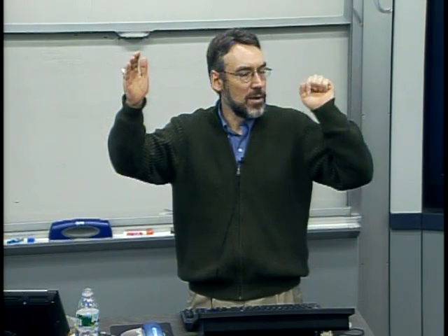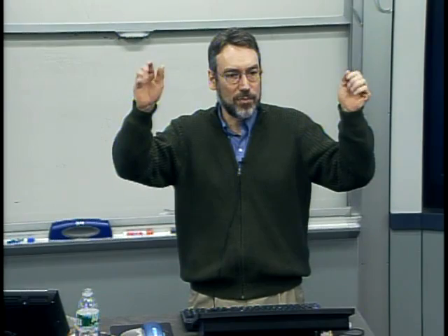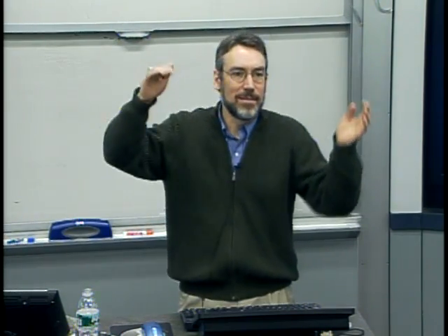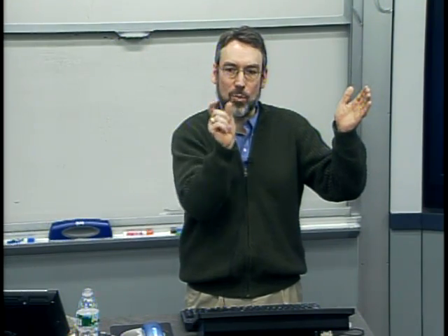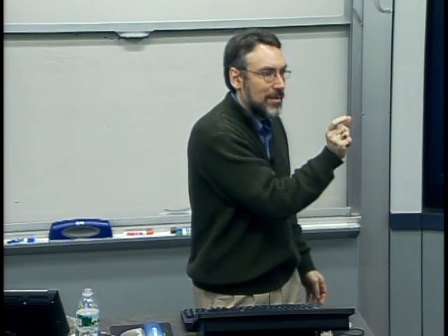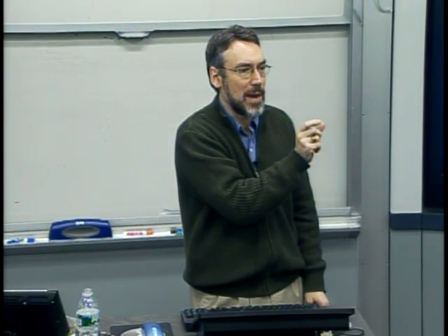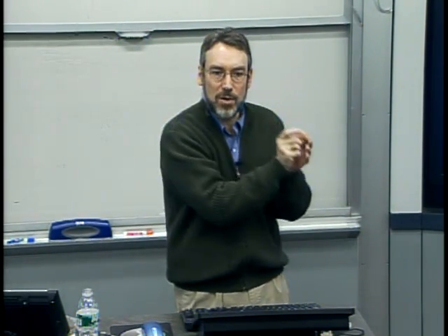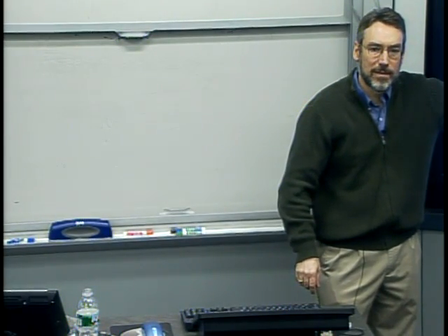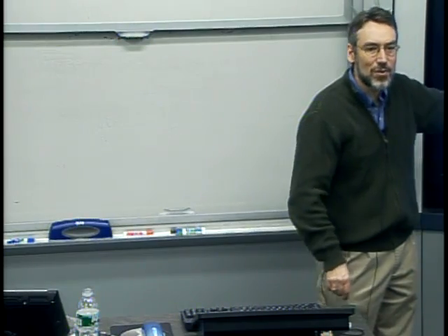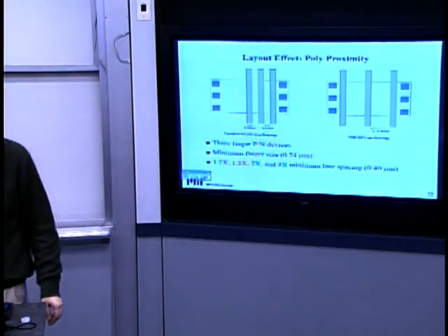If I were to say from center to edge, or from one edge of the wafer to the other, I have a systematic trend of about 10%, and I map that down to 1/10, because I've got 10 chips, that would be about a 1% variation you might expect because of wafer-level sources on each chip. But what we find is something like 4%.